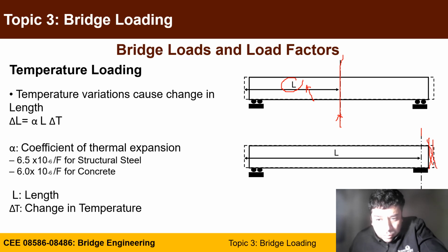You are not allowed to expand in this line. So it's fixed, and all the expansion has to happen in this line. So this is your distance L, okay? Because you are locking the deformation here, not allowed to move it, but everything will move this direction.